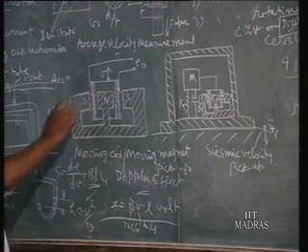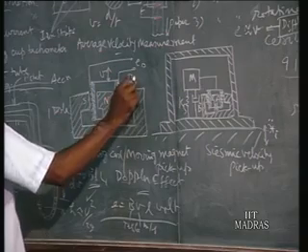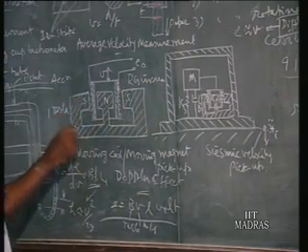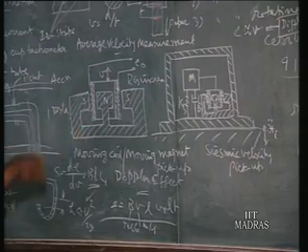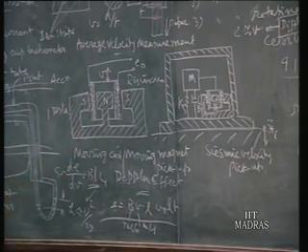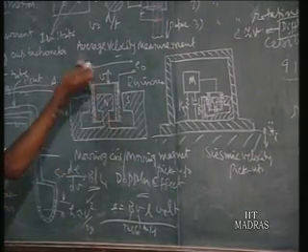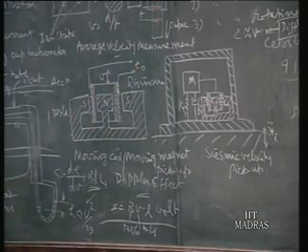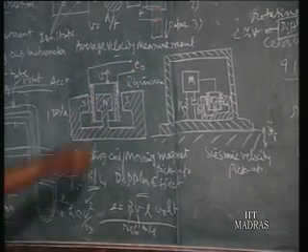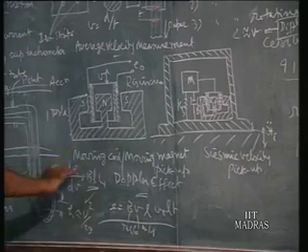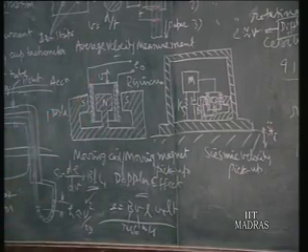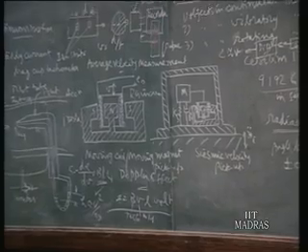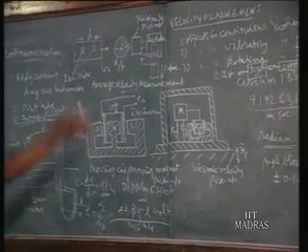So when you reduce the cross section, R is increased, the resistance of the wire is increased, because R is equal to rho L by A. A is in the denominator, so R is increased. So to measure the voltage, you require a voltmeter of very high input resistance. That is a drawback. So you cannot increase sensitivity as it is. There is a limit. Otherwise, this is the method very often used in measuring velocity in reciprocating bodies.